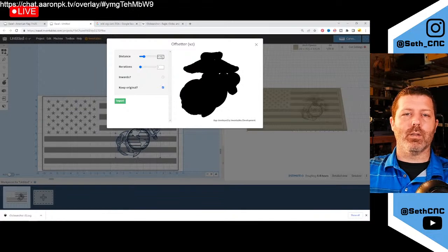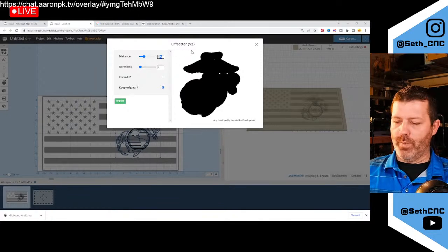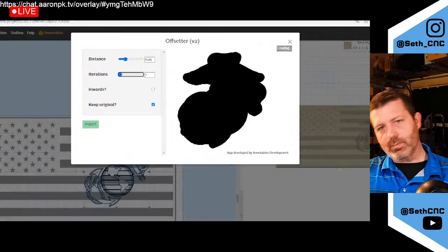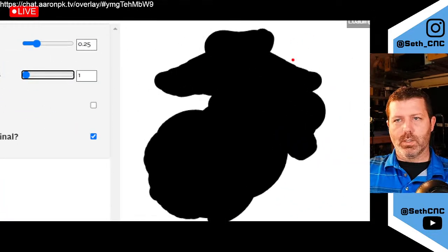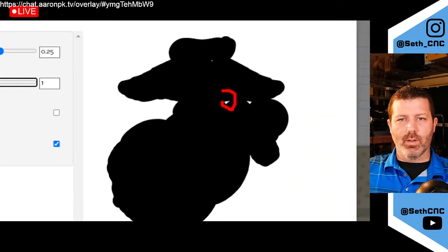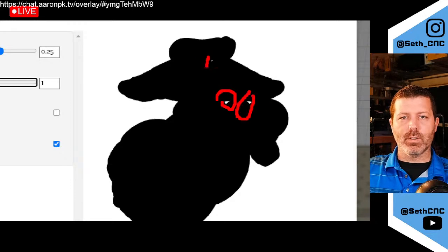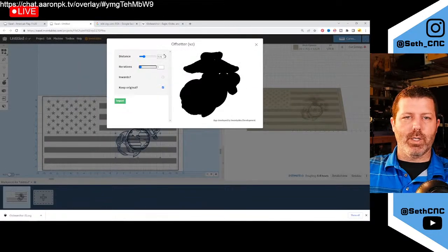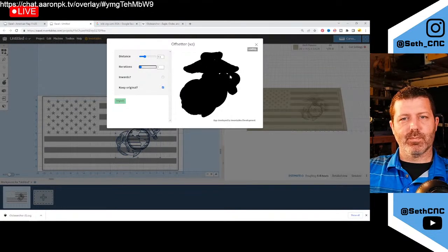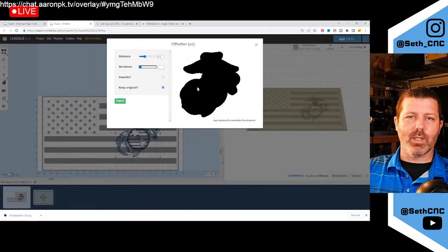In this case, let's go with quarter inches. Let's go a little bit bigger, just to set that up, because maybe you don't love the way this one here had a little... Let me jump back real quick and show you what I saw there. Once this loads up, there we go. I zoomed in too soon. We've got these little pieces that are showing here. You could go through and manually delete these out, or I'm going to cheat here and just increase the offset a little bit. There we go. So 0.3 is enough to get rid of those.